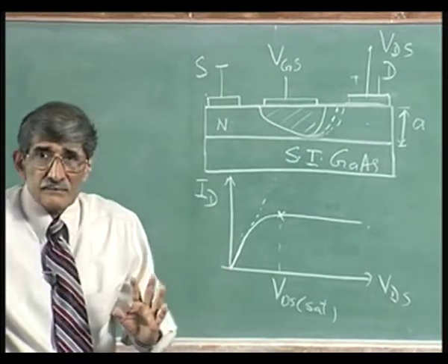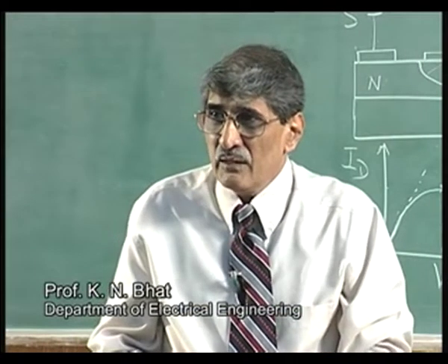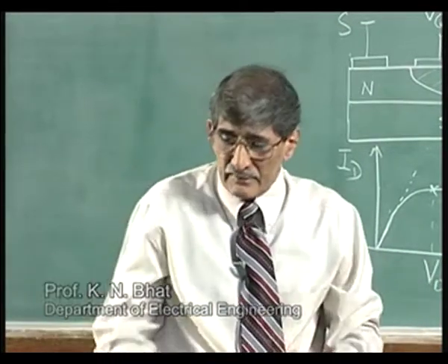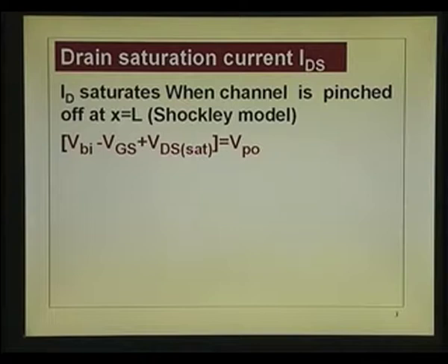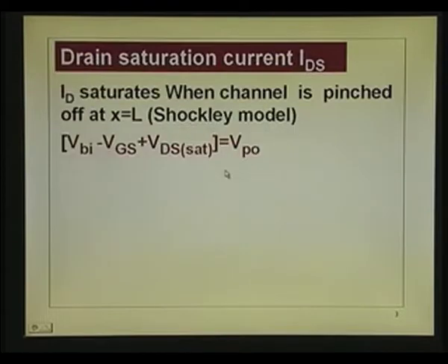With that introduction, or supplementing what we have been talking of yesterday or in the previous lecture, we will go ahead further with the discussion. But the key thing to remember is that what we have assumed is this point merges with this region, and beyond that point the depletion layer just spreads in the lateral direction, it does not move in the vertical direction. So, that is the current saturation.